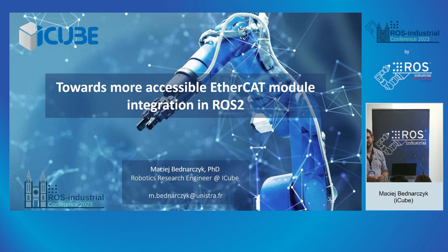But some robots that have EtherCAT drivers, like the Mecademic Meca500, have the whole system already available through EtherCAT. And for those, we couldn't find a good way to use ROS2 control and these joint-based plugins with the generic EtherCAT driver. So we had to write our own hardware interface for that. Do you have any thoughts on how you might be able to address those kinds of systems in a ROS2 control architecture with a more generic driver?